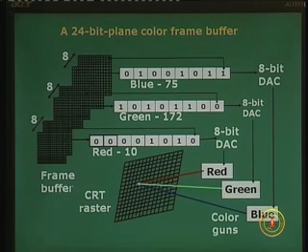We go to the next slide to see the complexity involved in a 24-bit full color frame buffer as given here. We have 3 groups of 8 bit planes, one for each separate color. On the left hand side, in the frame buffer, you see the black colored frame buffers, groups of 8, each group of 8 bit planes for red, green and blue respectively. The corresponding bit values are loaded onto the 8 bit registers, and this is a typical example. The zeros and ones are shown in binary, and the corresponding decimal value for blue is 75, you can check it yourself. Green equals 172 and red is equal to 10, 1010, that's 10.